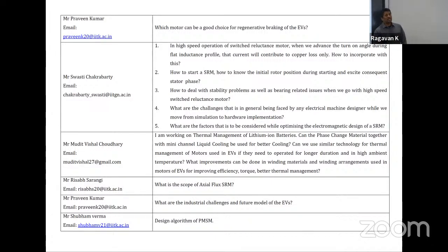So at the same time, your copper losses won't be any more than they were otherwise, right? I mean, you're applying the same amount of current, so your copper losses would still be the same. I square R stays the same, aligned or not aligned. The only thing that would change is you're going to send that energy into the core. So that's where I think you're going to have more of an issue, not the copper. Whatever you had before is still going to happen.